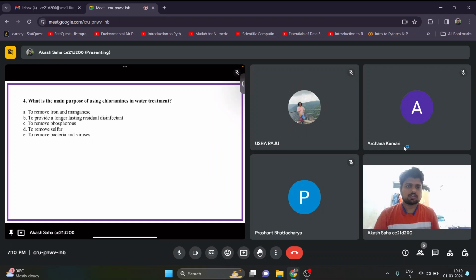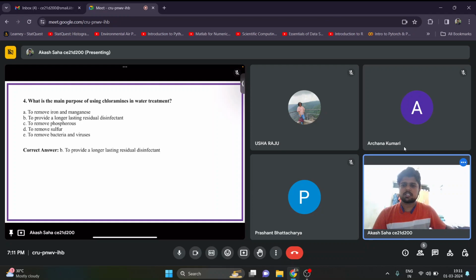Yeah, would anyone else like to answer? Any other thought process or any other option you think is correct? Okay, so basically it is the only correct answer. Option B is the only correct one because it helps to provide a longer lasting residual disinfection. Whatever residual chlorine we see is present after the destruction of these chloramines, and some part will remain as residual. So this will help give more residual disinfection for a longer period of time. So option B is the only correct one: to provide a longer lasting residual disinfectant.